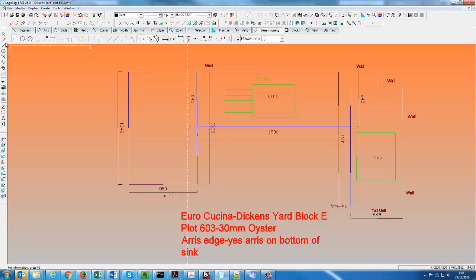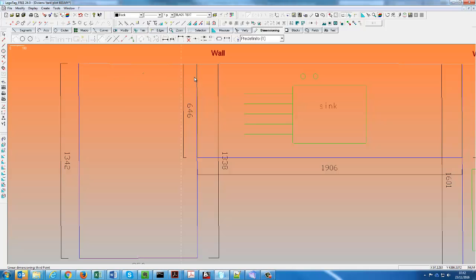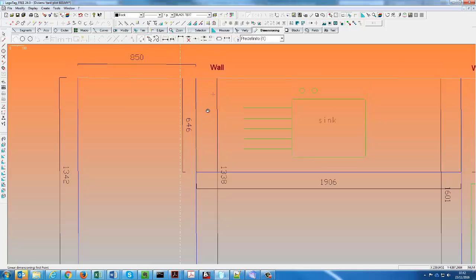So here the best thing to do is start off with, you only have to do 2 buttons, this F3 button and the F6 one later on, and that's only for two dimensions. So mainly it's this one here. And if you click, don't try and click the corner itself, click on the line, because if you click anywhere on this line further than near the halfway, if you just click on this half of the line, it will select that point. Again, anywhere on this side will select that point there. And that's point number 1.